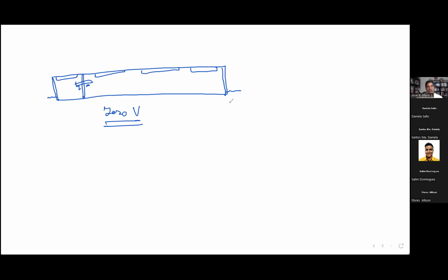So what I'm saying is that we can start recording in this position. So if this is time, we have two signals because we have two load cells. Okay, I'm going to show this. So this is voltage. Okay, it's floating. Now, when we install gently, always gently, please, this is going to increase, and eventually it's going to be in equilibrium.